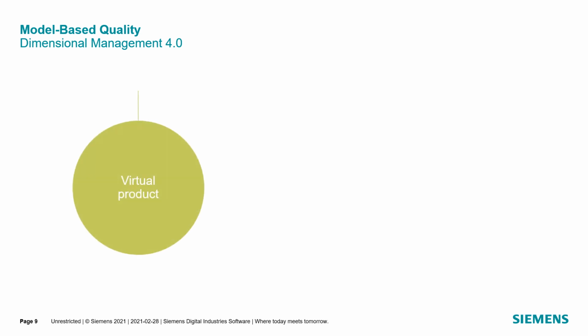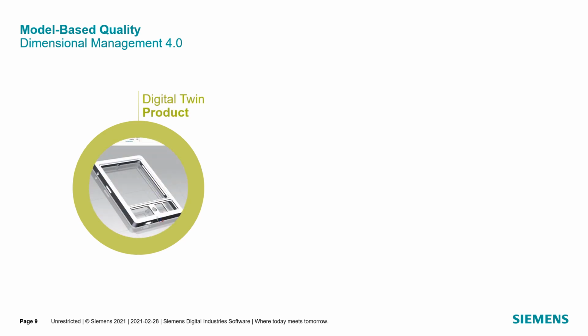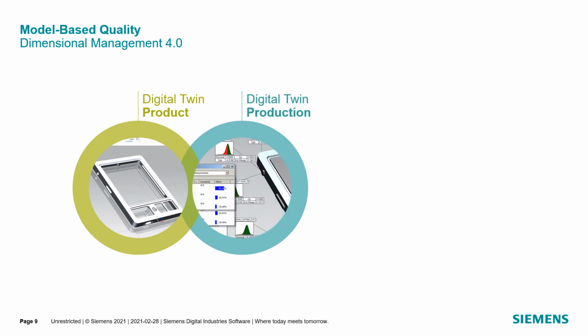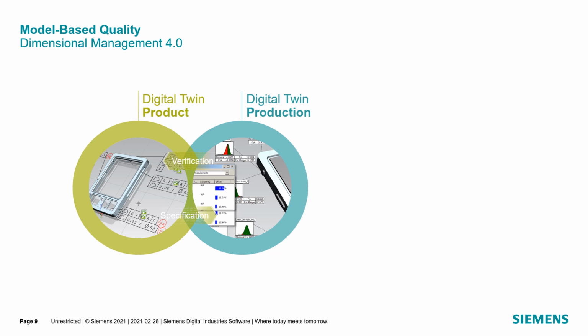It first starts with the virtual product, in 3D model or 2D drawing. VSA then virtually fabricates parts according to its GD&T design, assembles these parts together per real assembly processes, and then produces and inspects large numbers of such virtual assemblies to verify and validate part and assembly GD&Ts, and identify critical to quality PMIs to limit manufacturing and inspection asset costs during real production. This is a highly iterative process between design specification and engineering verification, until the product design including geometry and PMI are ready for release.